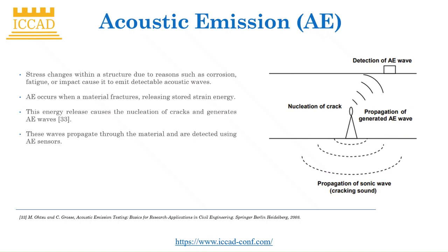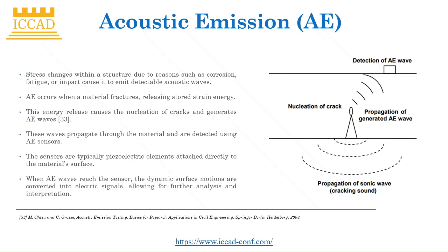These waves propagate through the material and are detected using AE sensors. The sensors are typically piezoelectric elements attached directly to the material's surface. When acoustic emission waves reach the sensor, the dynamic surface motions are converted into electrical signals, allowing for further analysis and interpretation.